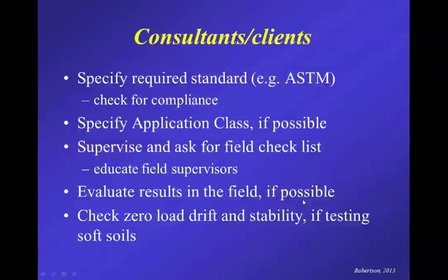And I strongly encourage that on bigger projects, whoever is put out in the field to supervise the work should have a laptop and should have software like CPT on their laptop. Because it's all digital data, they should be starting to look at the data and doing some preliminary interpretations in the field to get an idea of where the critical layers are, where they might want to take sampling, where they might want to do additional testing, etc. And of course, check the zero-load drift and the zero-load stability, particularly if you're testing in soft soils.